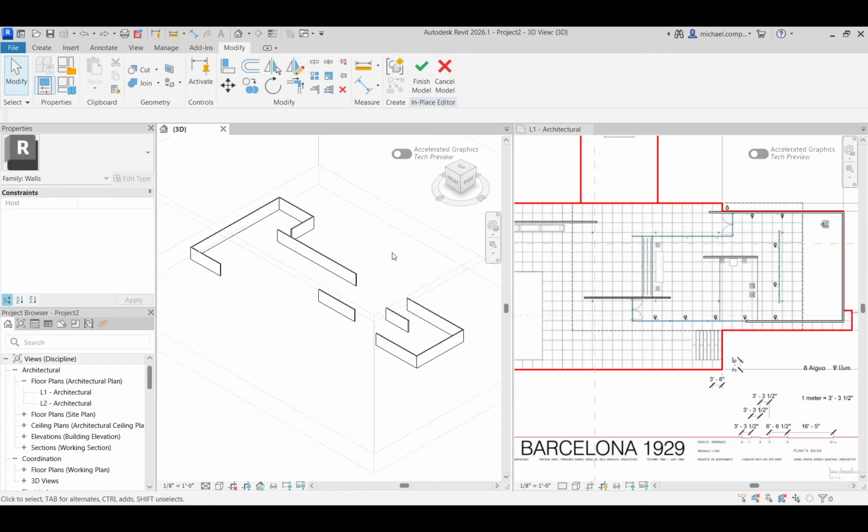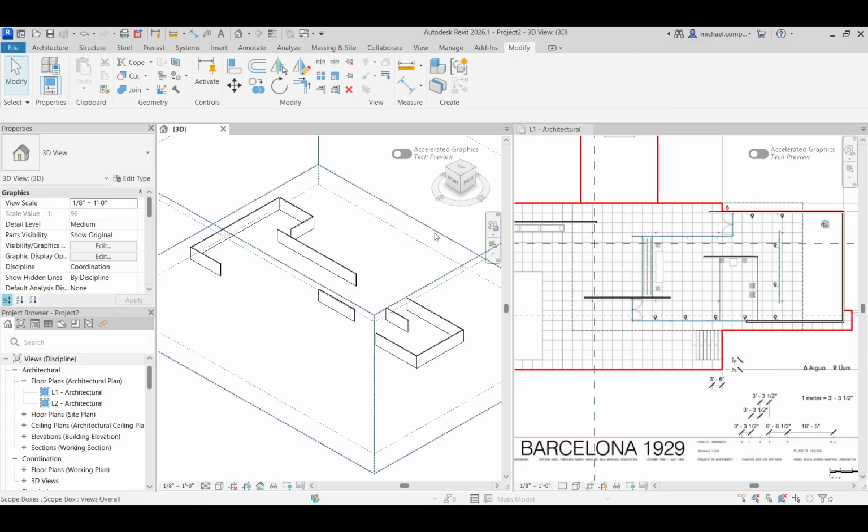So that's just something to be aware of when you're modeling using the sketch lines, which are the pink lines. I didn't mention those. The lines are pink in sketch form, and then when you close the polygon or close the sketch, they become black and white, and then also 3D. Okay, so I'm going to finish this one, and notice that that's not all the walls, and that's totally fine. But I'm going to finish this one from now, and I'm going to now show you the base. We're going to model the base. Okay, so finish the model.